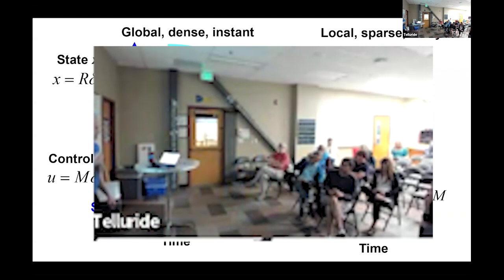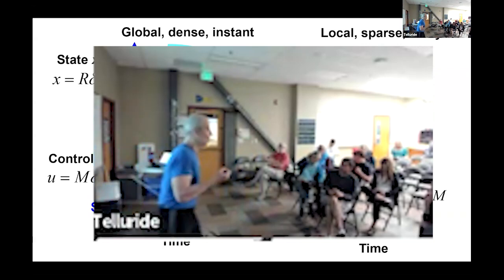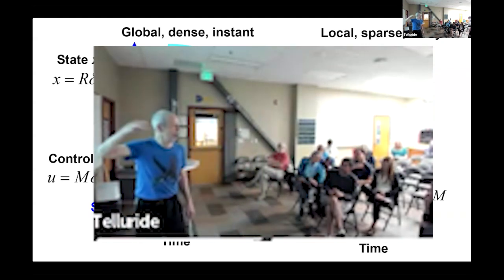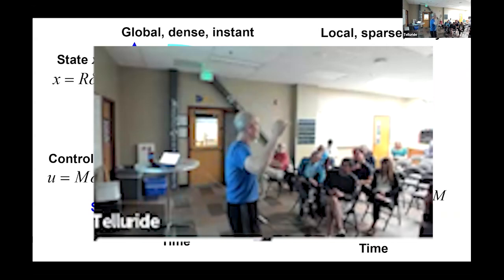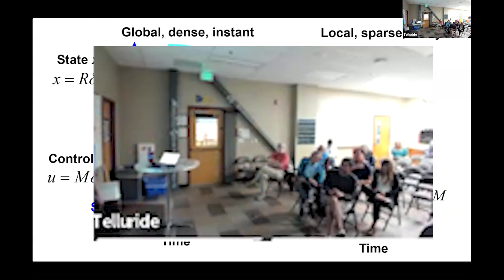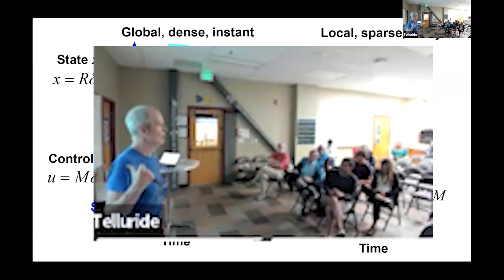But the point is, what you don't want to do is try to figure out what the A and B are. Because the dependence of this on A and B is some god awful mess back in the optimization stuff. So you actually want to work entirely in these closed loop M's and R's. And so that completely changes how you do any kind of learning in the context of this robust control.